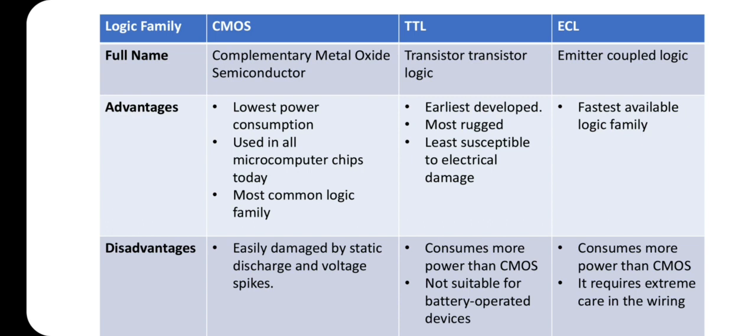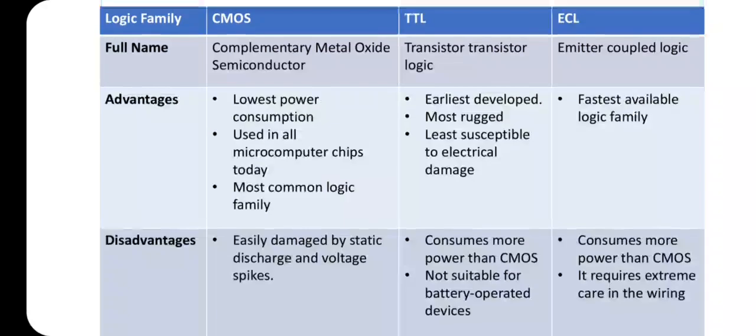Considering TTL. The full name of TTL is transistor-transistor logic. Advantage of TTL is earliest developed, most rugged, least susceptible to electrical damage. Disadvantages of TTL: consumes more power than CMOS. Not suitable for battery operated devices.